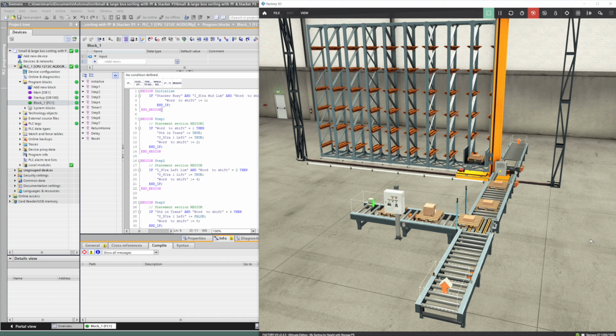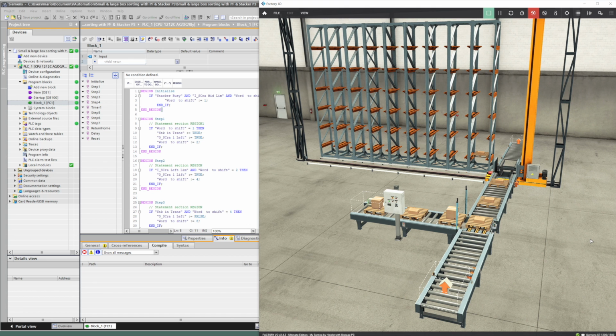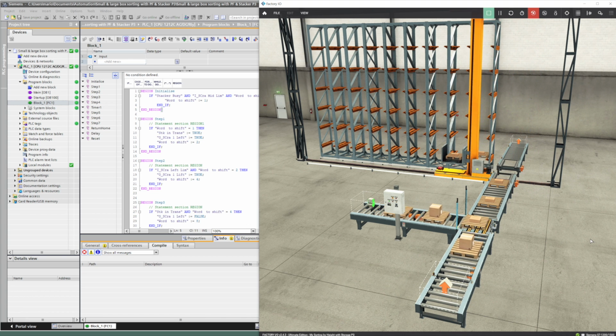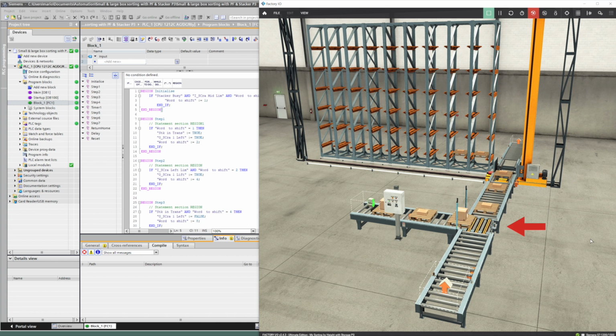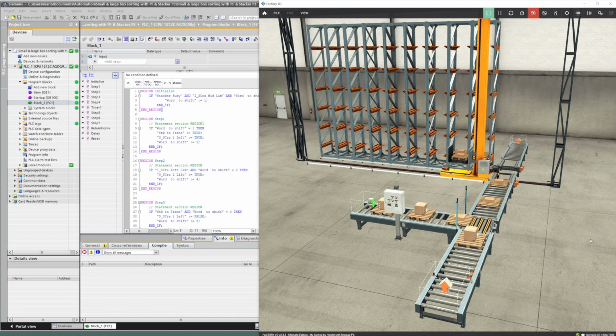Notice that the conveyors stop as soon as the small loader conveyor can't release the last small height box because the left conveyor is stopped while the stacker crane is busy. This is now a bottleneck which can be quite common in the real world, where one operation which is slow can stop another operation from happening. However, as soon as the stacker crane forks return and the next box is picked up, the large box is allowed onto the small loader conveyor, as we can see.